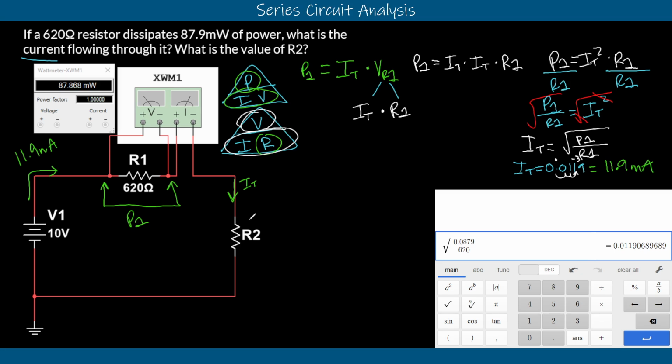So we need to figure out what R1 used in terms of voltage so that we can figure out what the voltage drop across R2 is. And that's actually using a law called KVL. KVL is Kirchhoff's voltage law, and it identifies the fact that if we have a voltage source, we can subtract the voltage drops that we know we lost, and we'll end up with the voltage that is left over, VR2. And that's what we're looking for. We're looking for VR2 here, so that we can compare it to what we know the current going through that resistor is, and then we'll be able to find the resistance of that resistor.